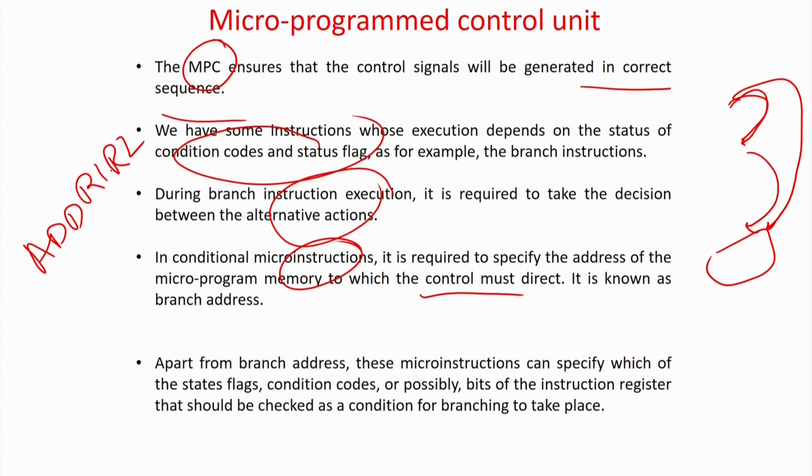For the time being, just take the fact that instruction fetch, decode and execute. So fetch, everything is similar. Whenever a new instruction has to be fetched, a fixed block of micro instructions which corresponds to memory fetch will be invoked. Invoked means the microprogram counter will start pointing to the first micro instruction which corresponds to instruction fetch. Then when an instruction fetch is done, we are decoding in the instruction register, and then accordingly